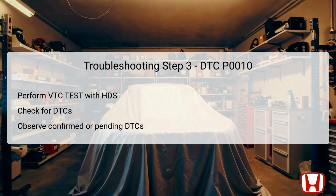Conversely, if it is not indicated, the issue may be intermittent or effectively resolved, and it may be worth investigating for poor connections or loose terminals at the VTC oil control solenoid valve and the ECM, suggesting that the system might be functioning correctly at that moment.